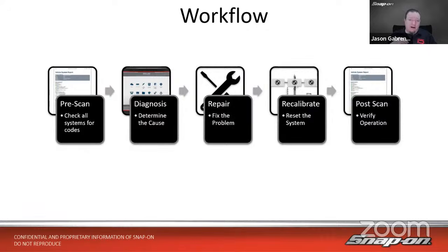When it comes to a diagnostics workflow, I would definitely recommend doing a pre-scan on every vehicle, just to see: are there errant codes in here that don't have lights associated with them? Make sure you scan it, check it, and communicate with the customer.